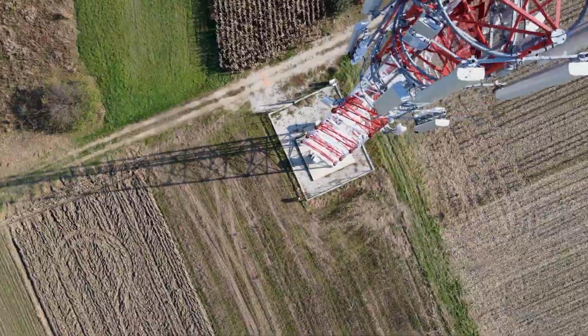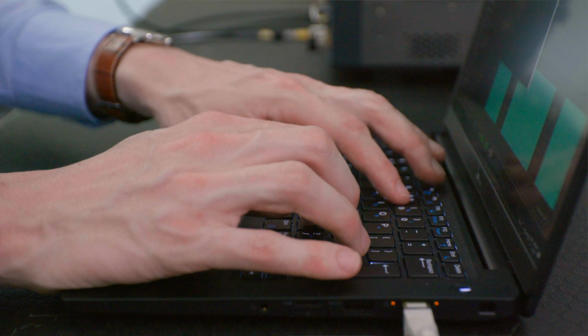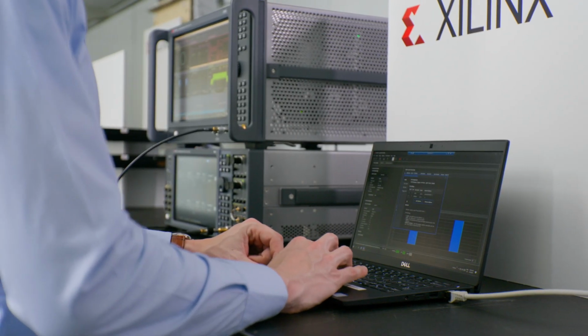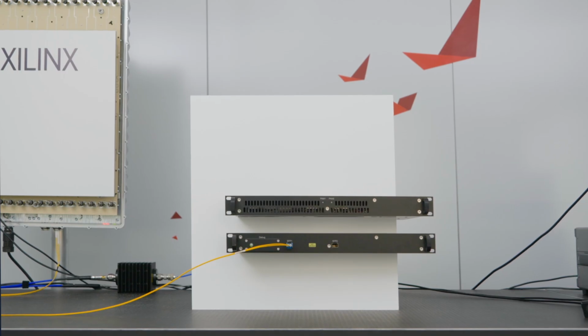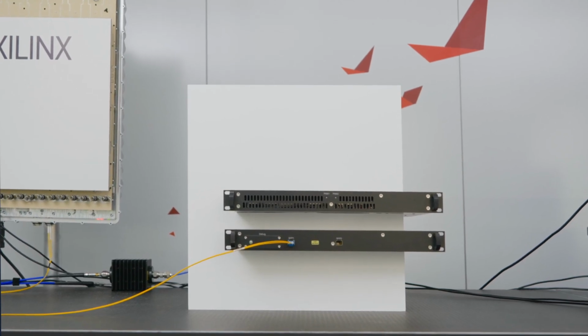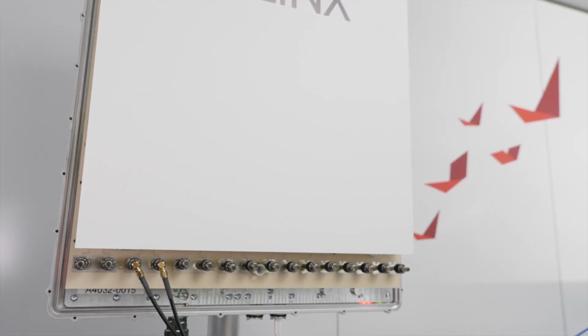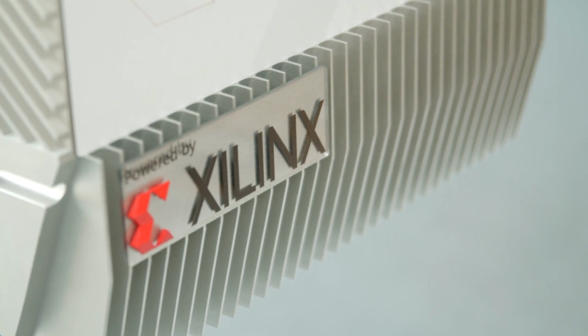With more openness, there are also new challenges for both the system integrator and the operator. The first challenge is efficient O-RAN compliance testing, to really ensure that a base station and a radio from different vendors interoperate correctly in a network. The second challenge is coexistence. While CPRI-based equipment is still running in a network and O-RAN compliant equipment is being rolled out, operators really need a cost-effective way to multiplex both solutions over a single fronthaul link.